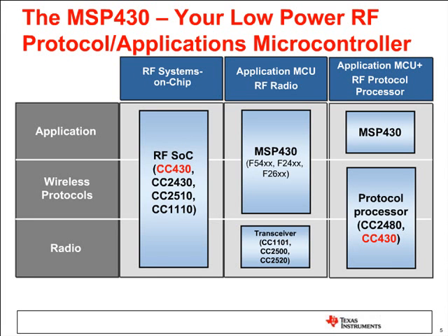We also had the option, of course, and many customers have been successful, for example, with the 5438 mixing it with a 2520. But the point being here, in the application MCU plus the RF radio, is that the radio is just the physical layer. It's just a radio. It doesn't have an integrated MCU, and you send it all the data that you transmit and receive all the data back from it over the SPI.